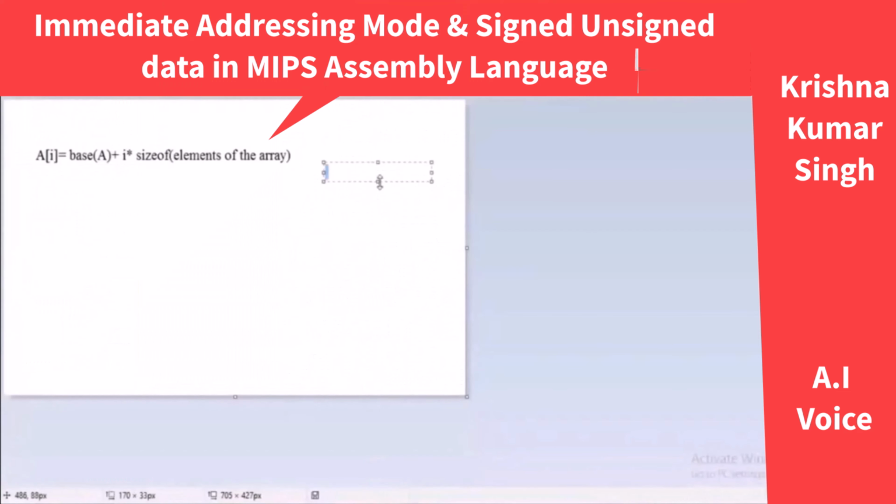In 8086, we have some general purpose registers like AX, and each one has 16-bit capacity. So you can write an instruction like ADD AX, number. But this is a CISC instruction, Complex Instruction Set Computer. In 8086 assembly, the first one is the destination, so AX and the number will be added together and the result will be written back in AX, the accumulator.